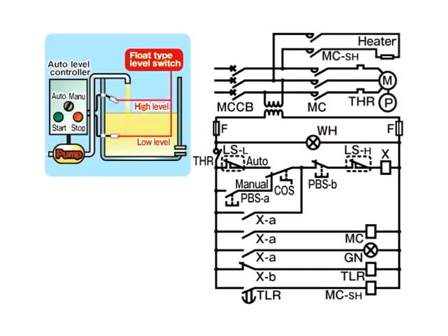However, the THR relay does not reset automatically. If the relay is left as it is, the tank will become empty. This is because even though the LSL float falls along with the liquid level, the motor is not operating automatically.